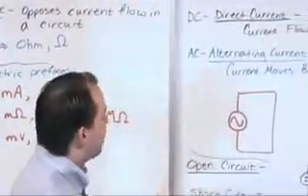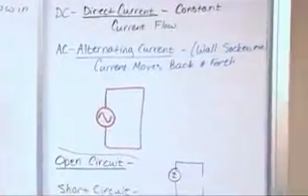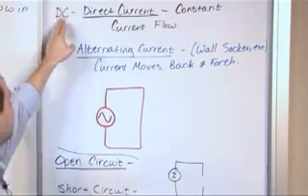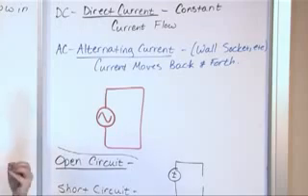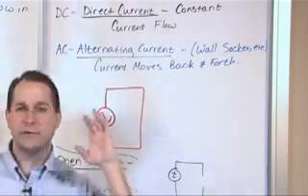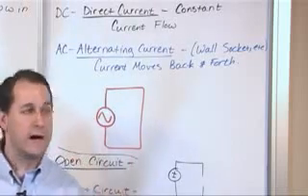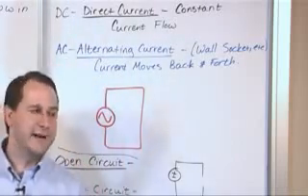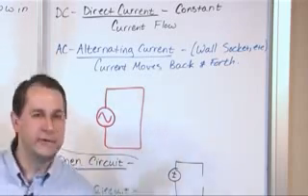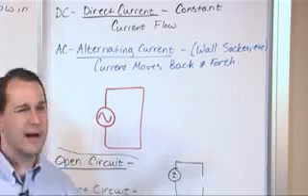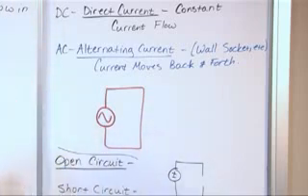And then we talked about some other random definitions that people have heard over the years of growing up. Direct current DC, alternating current AC. This guy is usually coming from a battery, some constant current source, usually a chemical reaction is giving you a constant voltage, constant current coming out all the time. Alternating current comes out of your wall. The reason it's alternating is because it's easier to generate, because you have rotating generators and you have easier transmission to the homes. There's a lot of theory in that, but that's basically the deal.